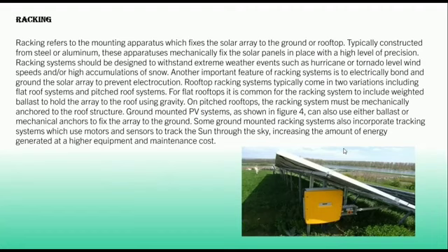typically constructed from steel or aluminum. These apparatus mechanically fix the solar panels in place with a high level of precision. Racking systems should be designed to withstand extreme weather events such as hurricane or tornado level wind speeds or high accumulations of snow. Another important feature of racking systems is to electrically bond and ground the solar array to prevent electrocution. Rooftop racking systems typically come in two variants including flat roof systems and pitched roof systems.